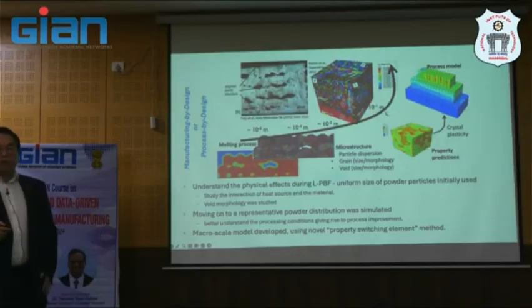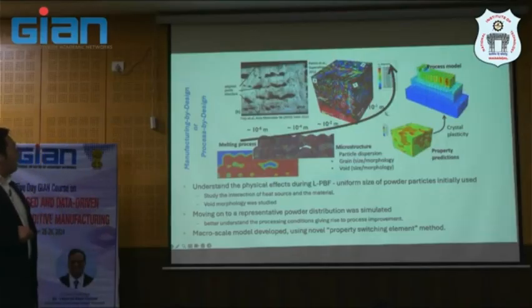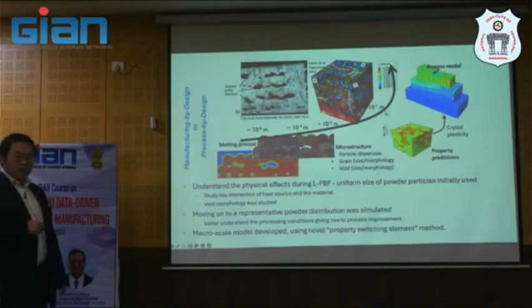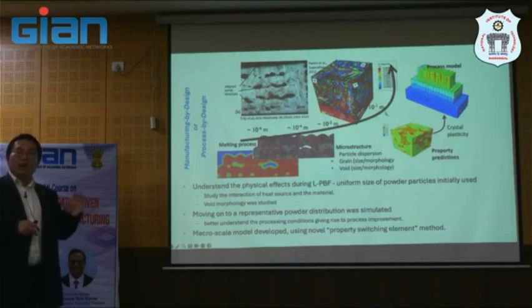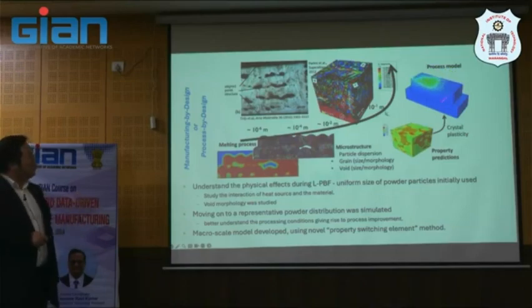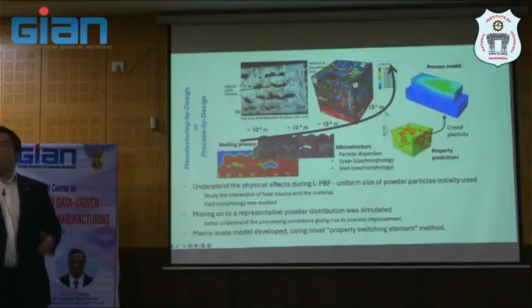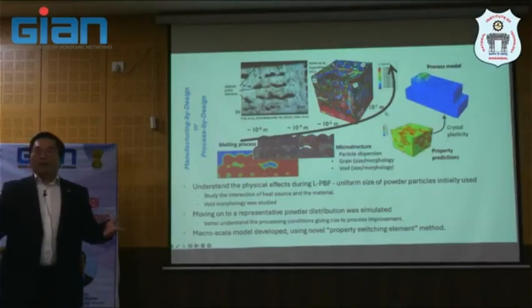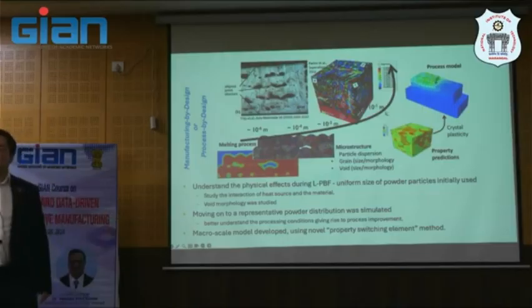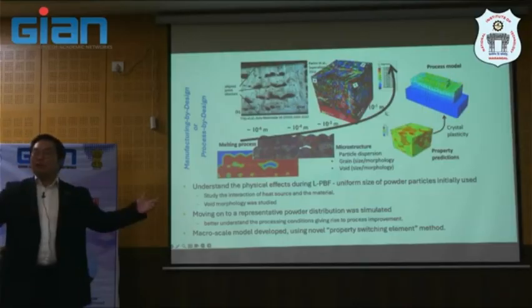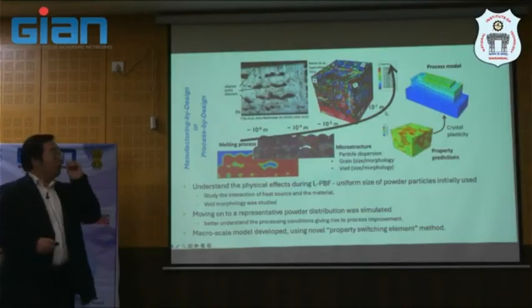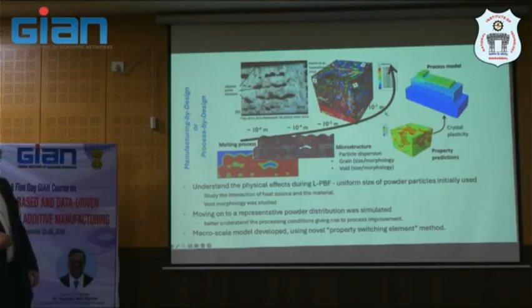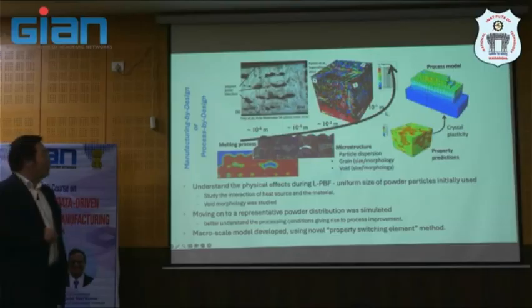This is an important question, because we have to understand the melting process at the 1 millimeter length scale. That is the reason why we do the simulation at the 1 millimeter length scale. Otherwise, if you use a mesh of 250 microns, 1 millimeter is still too small actually for the big model. So 1 by 1 by 1 is still too small. And that is how we choose the length scale of the problem.